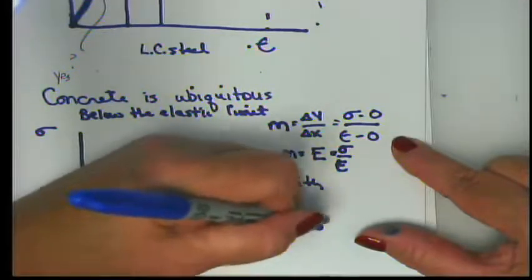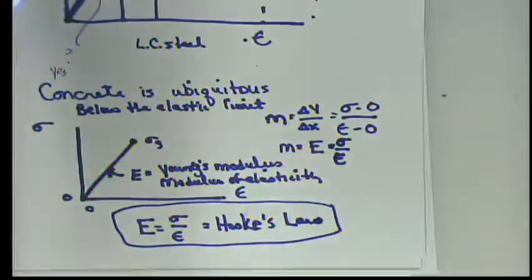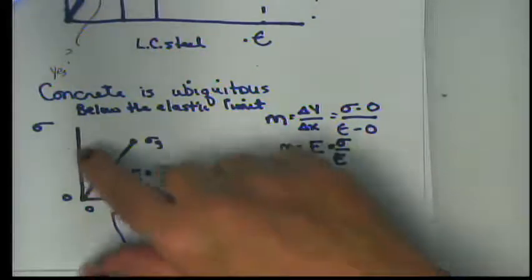And Hooke's law is a very useful computational tool for materials behaving within the elastic limit. So we're going to extend our conversation about this at least on Wednesday and maybe a little bit on Friday. But there are a couple of things about Hooke's law. Hooke's law only works in the elastic limit, and it only works for normally behaving materials. It also tells you nothing about the strength of the material. It tells you how stretchy the material is.